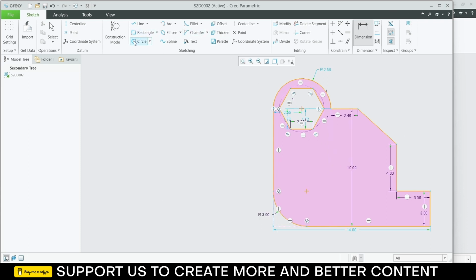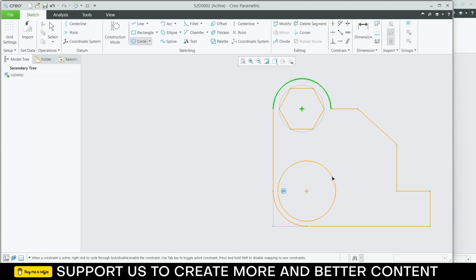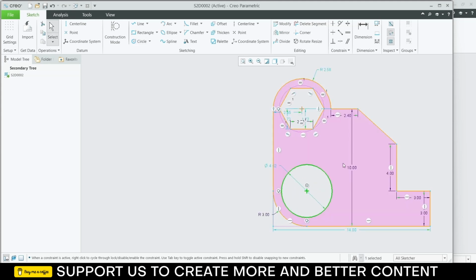I need to draw a circle as well. Select this point. Draw a circle shape. Click on the middle mouse button. Double click on it. Type 1 point. Just, you know what? I want to type radius. Currently it is diameter. So what I can do? Click on it. Simple right click. Click on this icon. Now type 1.6. So this is radius. Okay. So you can know how to choose radius or diameter as per your requirement.